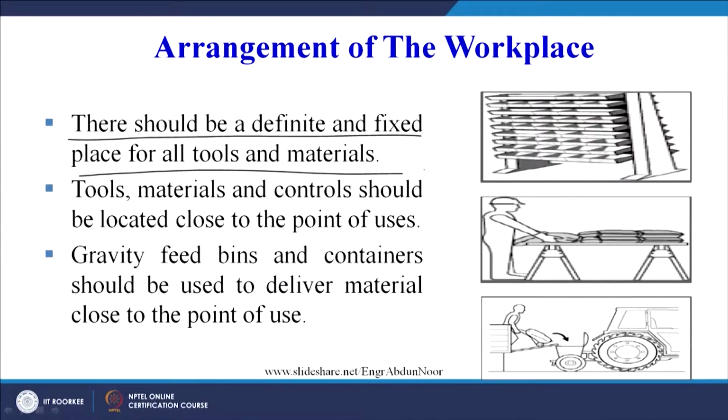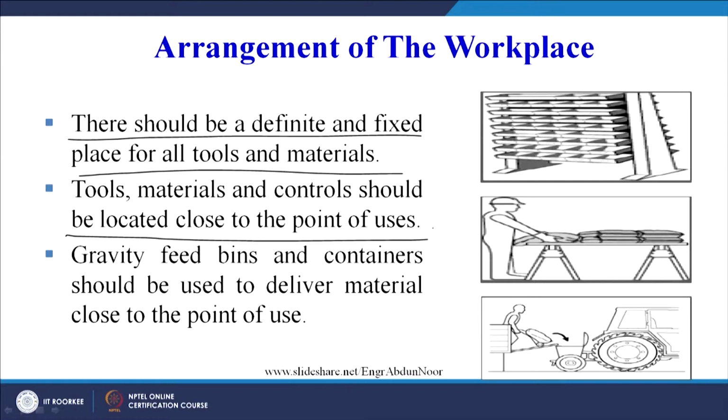Tools, materials and controls should be located close to the point of use. So if I am using it as a pen, and if it is put at this point, every time I have to use, I have to pick this pen from a distance, that can easily be avoided if it is placed at a point close to the use. So tools, materials and controls must be located close to the point of use.